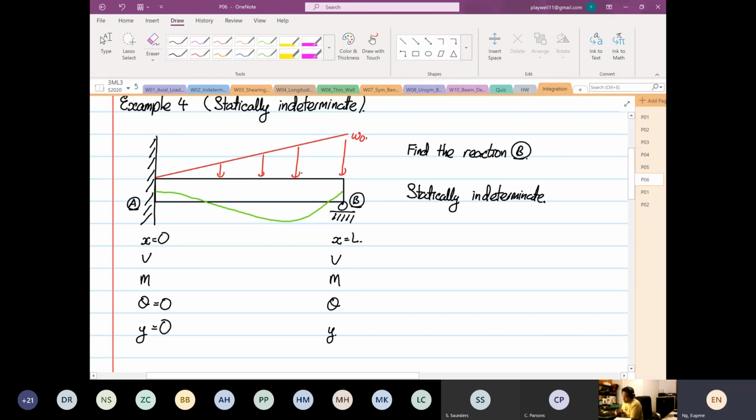Over on the other side, we know that M is equal to 0, right? Because when I remove the support at A, B will rotate, and y will be 0. And at x equal to 0, theta is equal to 0. So if I draw a chain line at this point, where it's in green, the slope is equal to 0. I don't want you to memorize this either. Memorizing is something that will not work at all.